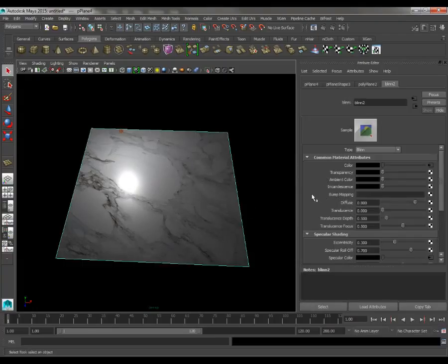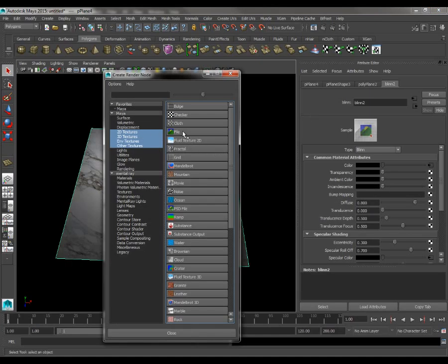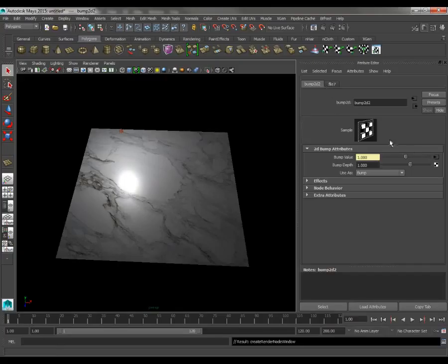Now we want to input our normal map into our bump mapping section here. When you're first starting off doing Maya, it's not very apparent where you put these maps. But we want to put it inside the bump map section. So clicking our little guy at the side, we'll get this menu. We want to tell our shader to not use a bump map, because you can see here we've got use as bump, and we don't want that because that's not the value that we're going to be inputting. Bump maps are based off a black to white value, just like a specular map, but we want a normal map which is based off a completely different value.